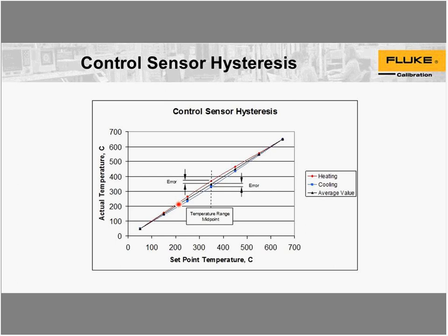As we go up, the temperature controller will react to the sensing element. Actually, by the time you get to the middle, you reach your maximum error. You go to the top, everything comes together, and as you go down in temperature again, you reach the middle of your excursion. You have an error in the opposite direction, and eventually it repeats itself every time you go up and down.